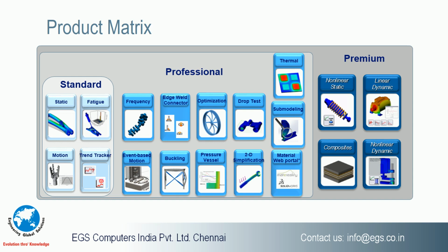And event based motion analysis is similar to time based motion analysis, but we can give a feedback system. For example, let me take the same example of the automatic packing industry. What I can do in event based motion analysis is say, okay, the moment the package has reached this station, another packing component needs to be moved. What we do in time based motion analysis is say the shaft should rotate for this much time, and this component should move from a 0 second delay. But in event based motion, we specify that once the component reaches station A, then the component should go to station B only after it has reached station A, like that.